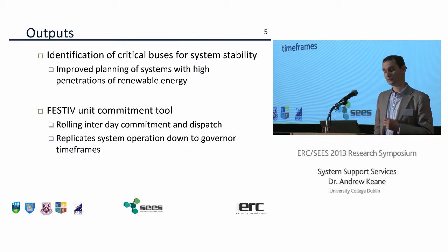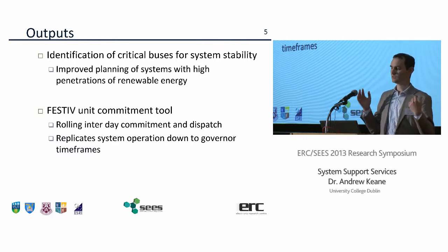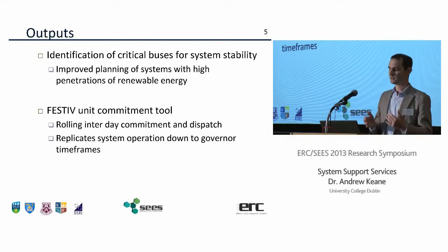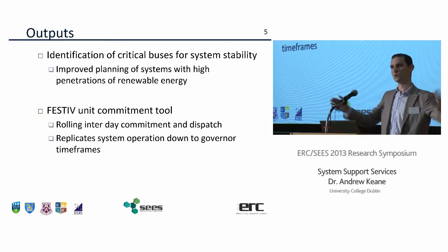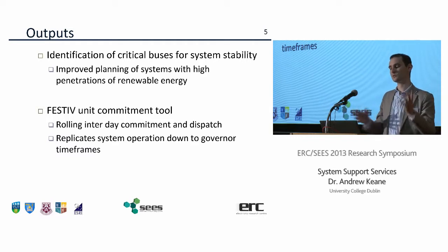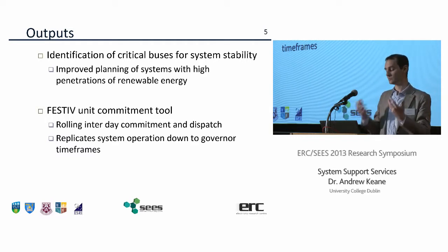And finally then, the festive unit commitment tool, which is developed by Eric Ela and James Ryan, which is a rolling intraday commitment and dispatch tool. So without going into too much detail, essentially what this tool can do is the classic unit commitment generator scheduling problem, but it's now capturing dynamics right down to governor timeframes, so right down to seconds, back up to hours and days ahead, and trying to capture and optimize those dynamics and essentially the scheduling of the plant on the system.